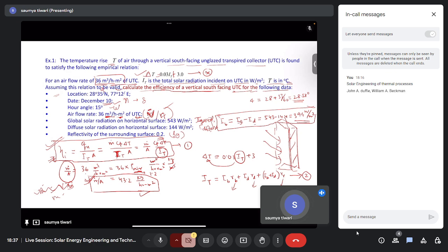And we know the IT, the total solar flux falling on this wall will be given by this equation that we have already seen earlier, right? So what we need to calculate is the IB, ID and IB plus ID, your global, diffuse and beam radiation. You need to calculate this R for beam radiation, R for diffuse radiation, and an R for reflection, right?